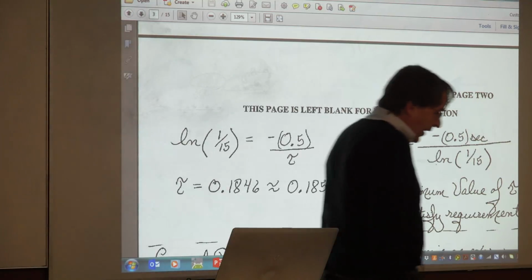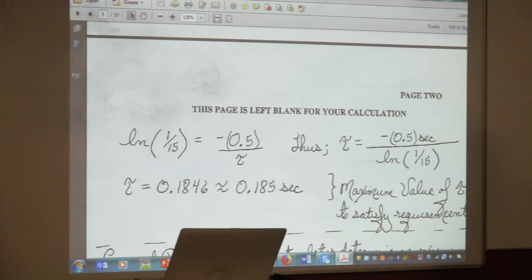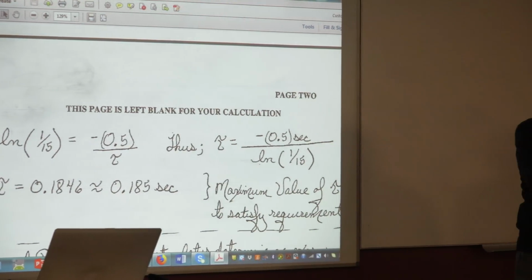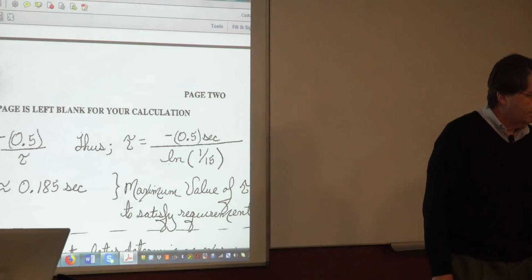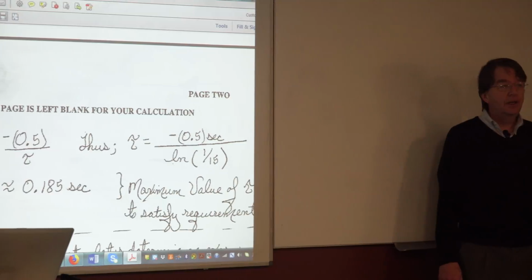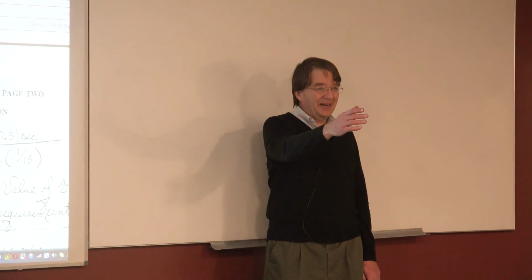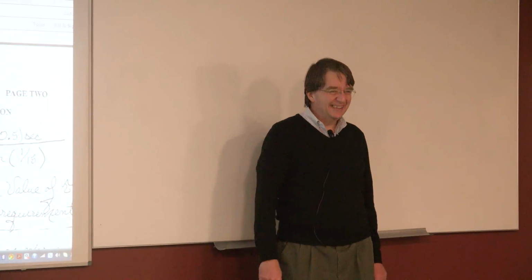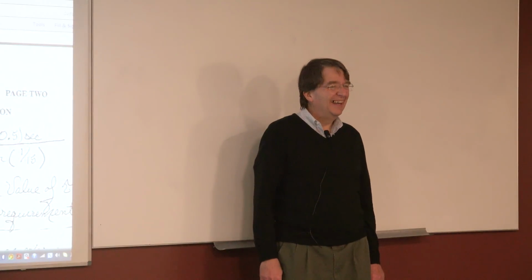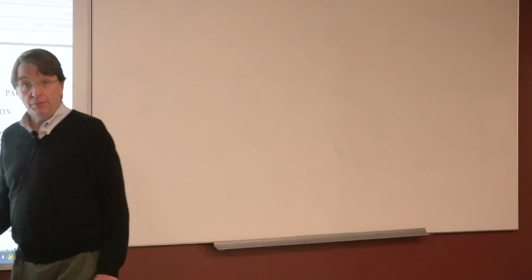So that means if I have a first order sensor with that value of tau, I will reach 90% of my final value in half a second. Okay. First part of the problem is done. To my colleague who we locked out, how we doing, my colleague? We're doing good? All right, good, good. All right. So that's the first half of the problem.